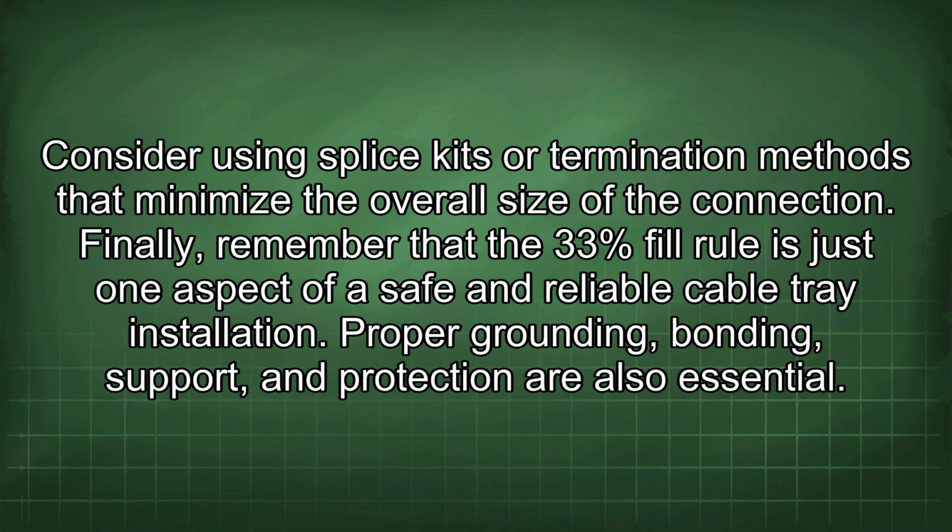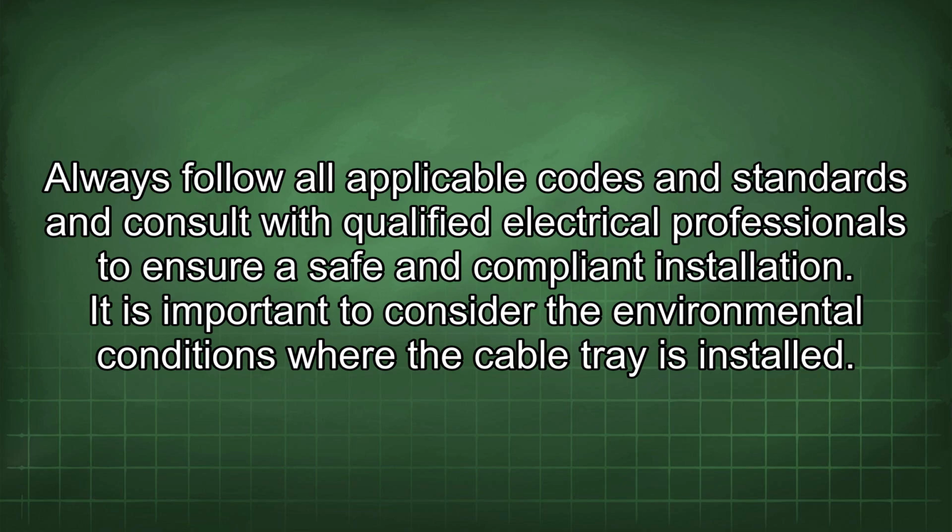Finally, remember that the 33% fill rule is just one aspect of a safe and reliable cable tray installation. Proper grounding, bonding, support, and protection are also essential. Always follow all applicable codes and standards and consult with qualified electrical professionals to ensure a safe and compliant installation.